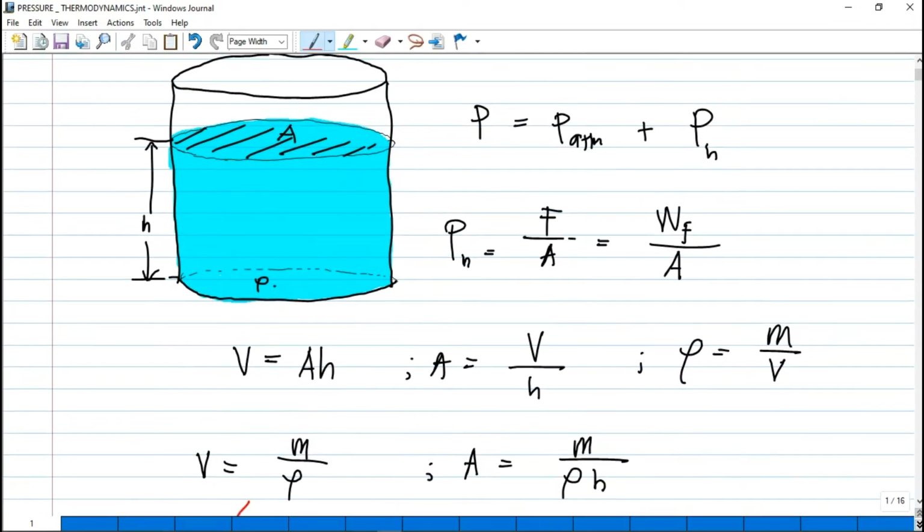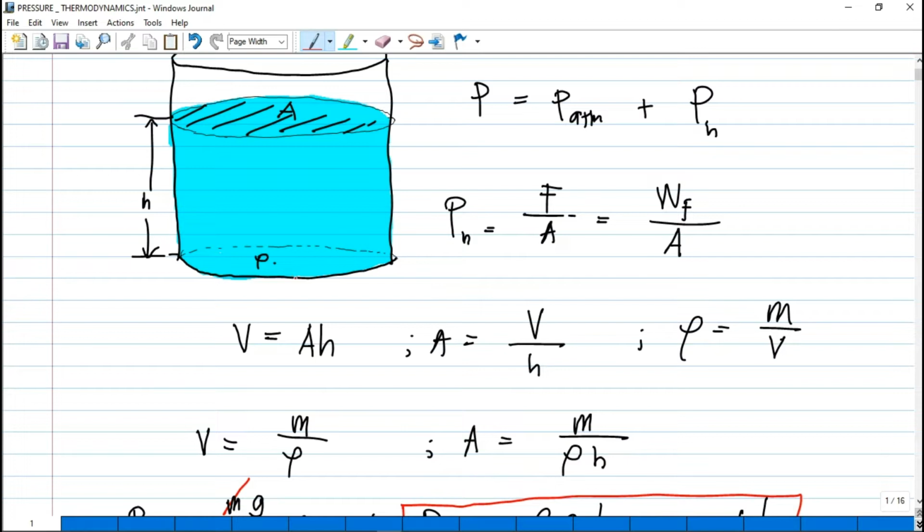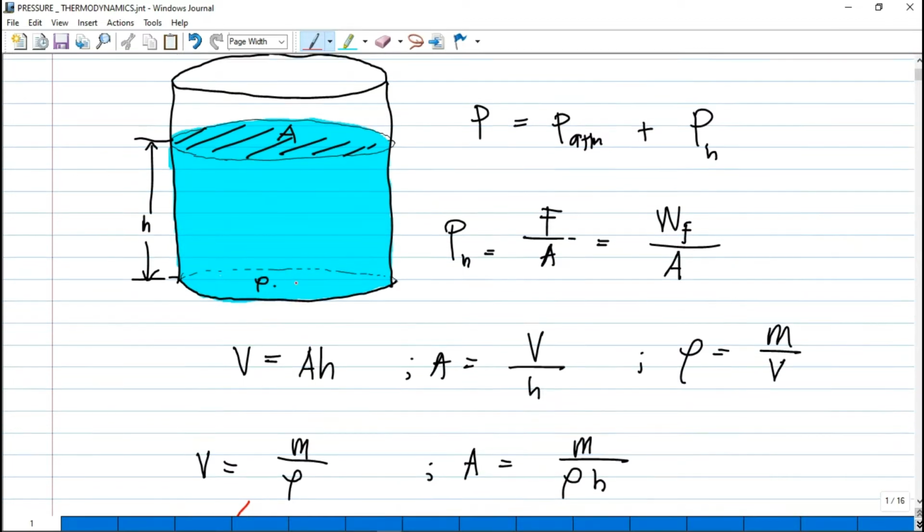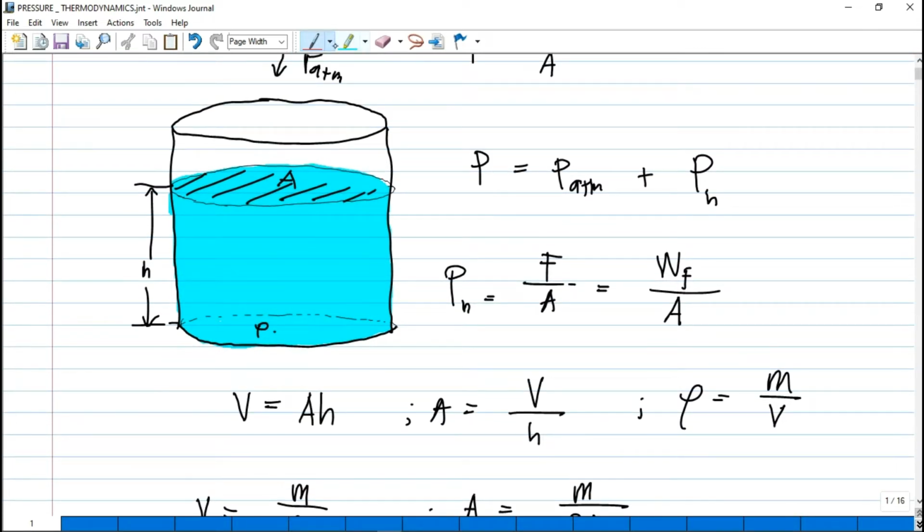So, therefore, yung pressure at the bottom is just equal to atmospheric pressure plus pressure due to height, which is density of the fluid here, yung fluid na ginamit, times the acceleration due to gravity, then yung ating height. So this pressure at the bottom of the tank, yan yung true pressure niya doon.